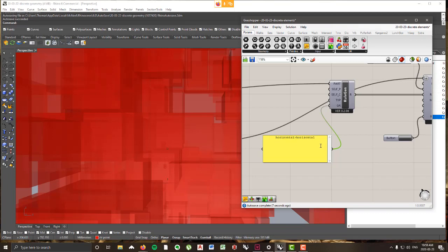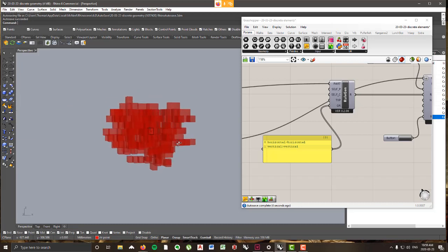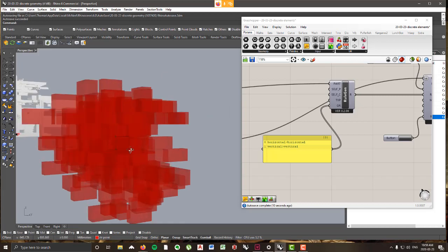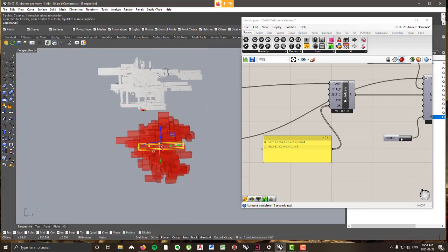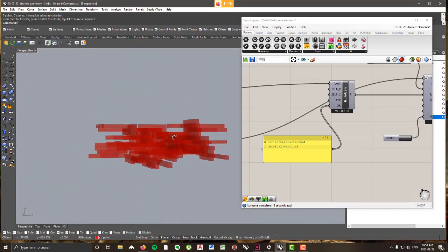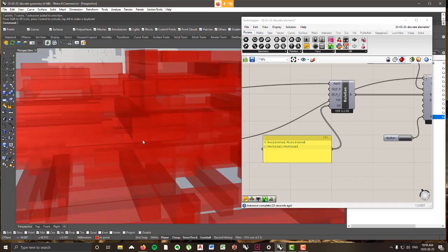I'll hit enter to start a new line. And now maybe what I'm going to do instead is go vertical greater than vertical. So vertical to vertical, I'll click outside, hit reset. And now you'll see what happens is we don't get those rotations anymore. We're just getting stackings. So essentially what I mean is if I maybe just stretch this out a little bit so it's easier to see. Now we're just getting stackings of objects, so you don't get any rotated pieces.